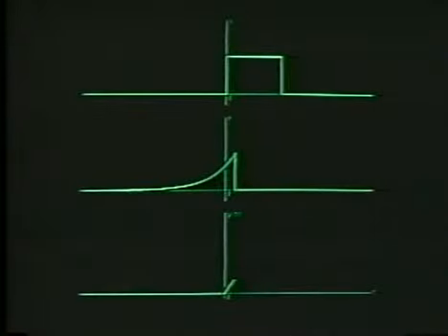So the bottom trace shows the result of the convolution, here shown as 0, and it will continue to be 0 until t becomes positive, at which point we build up some non-zero term in the integrand.